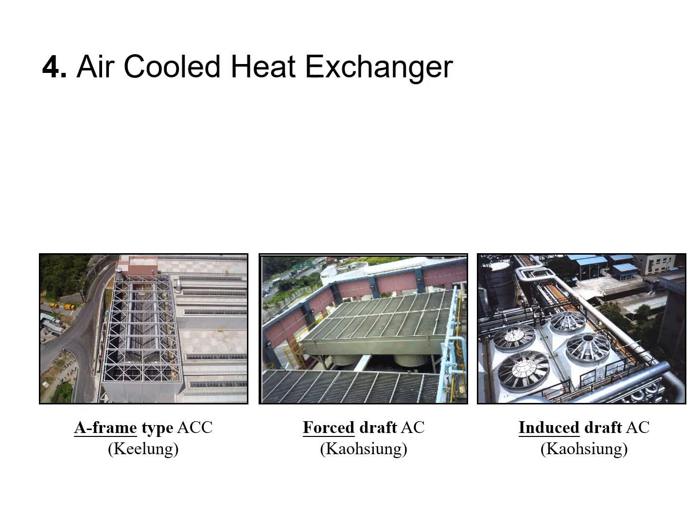Chapter 4. Air-cooled heat exchanger. Here, we show 3 different devices set up in 2 cities in Taiwan, Keelung City and Kaohsiung City. The picture on the left is of an A-framed type air-cooled condenser. In the middle, you can see a horizontal forced draft air cooler. On the right, there is a horizontal induced draft air cooler.